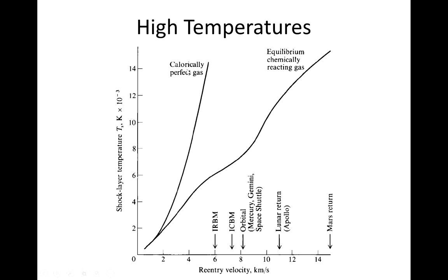It's not even a function of temperature. So it's called a calorically perfect gas. But as the Mach number increases, we have to assume that the specific heats Cp and Cv are functions of temperature and possibly functions of temperature and pressure. So therefore, a different thermodynamic model will be needed.